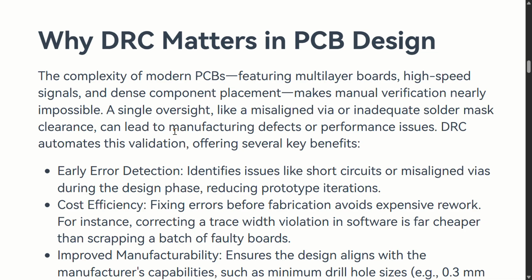So DRCs are always safer to follow, but at certain times, for example at a power rail, we usually put 5 mm or 3 mm as spacing, not 0.15 mm. Depending upon the circumstances we may slightly deviate, but we are not violating. Putting a little more spacing is not considered violating the DRC.